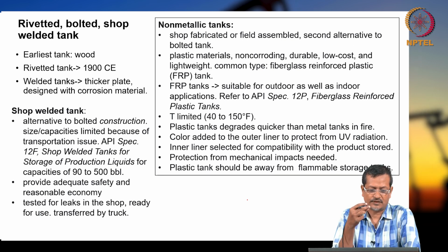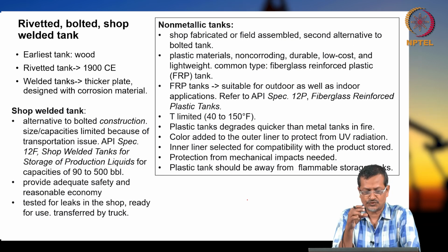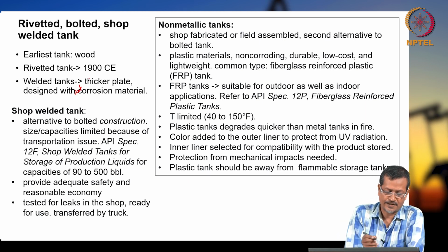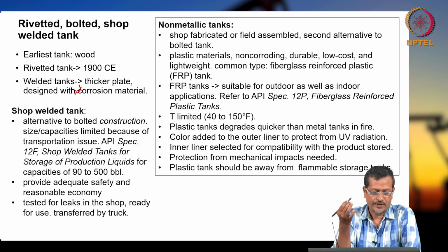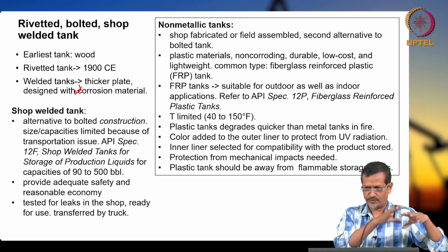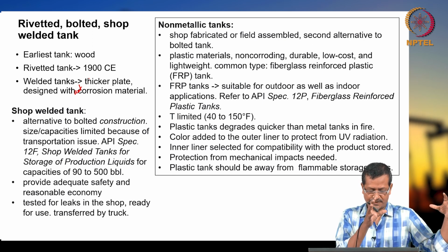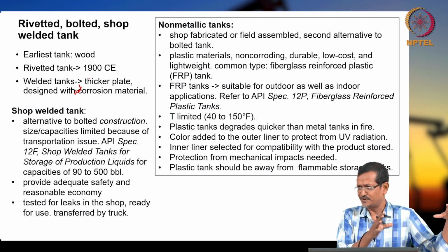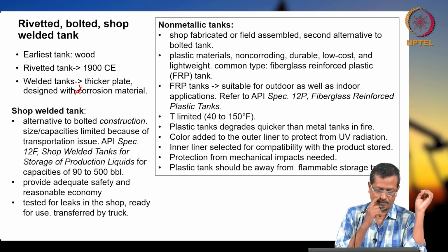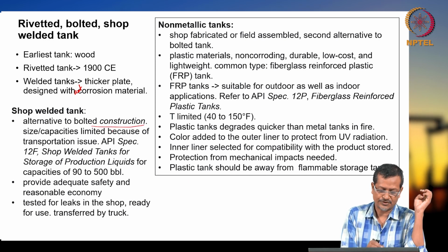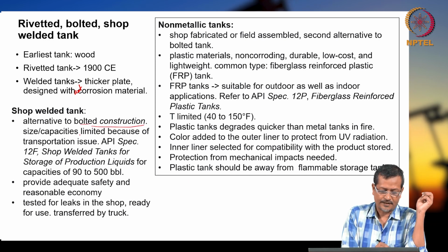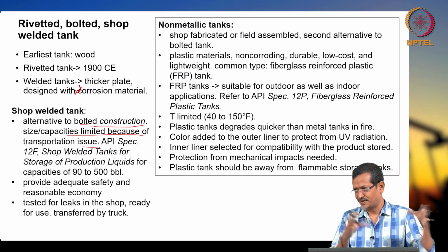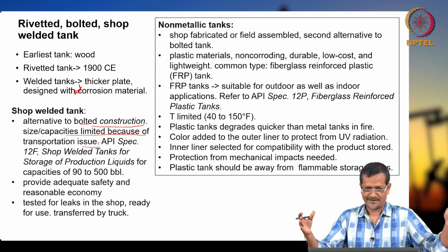So, they took thicker plate designed with anti-corrosion material. Shop welded means there is a machine shop, and you are welding there. Then from there you carry it to your location, okay. So, that means you cannot make a very big system. It will be a smaller system when you are talking about shop welded. It is an alternative to bolted construction, I will discuss bolted later. Size and capacity are limited because of transportation issues, because you have to carry it, and one truck size is limited, right.